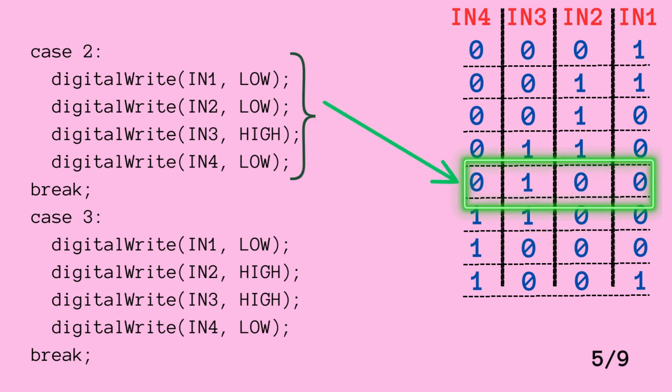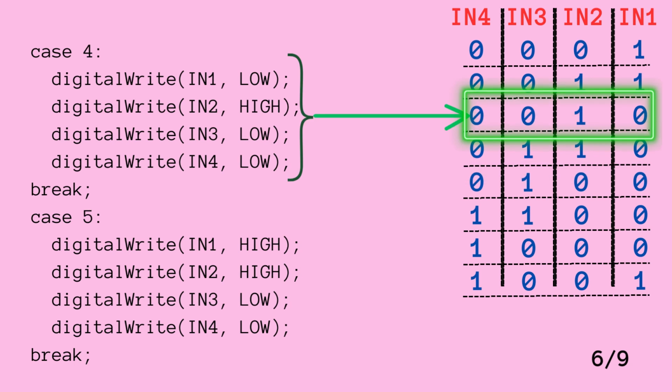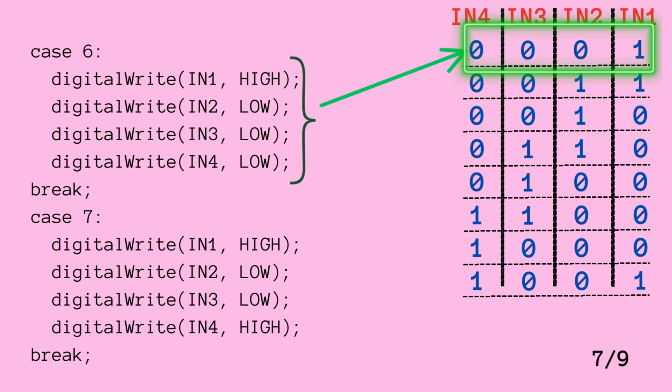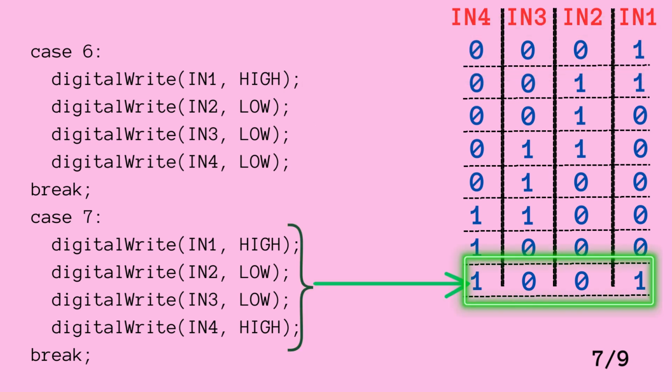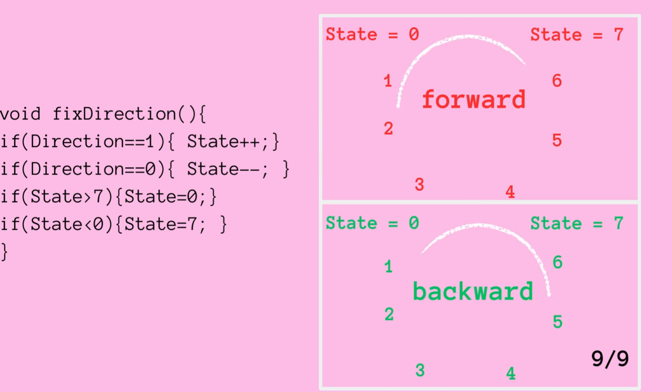Alternatively, it could be implemented through if-else structure also. In switch statement, various states are taken through case declaration. Each section of case is executed depending on the variable state. Hence, progression of logic states assigned to the variable state determines the sequence of execution and hence the direction of rotation.